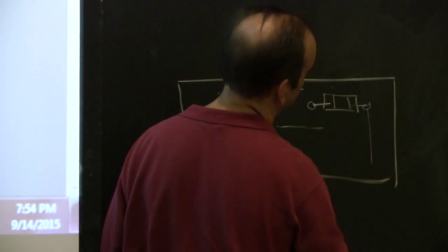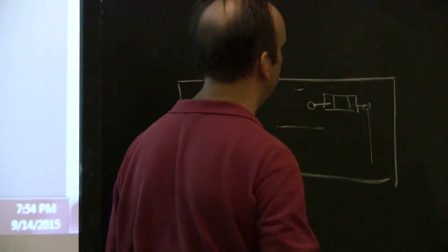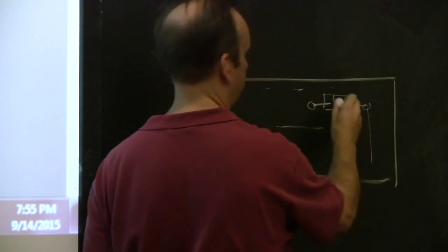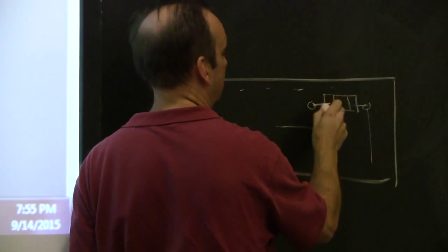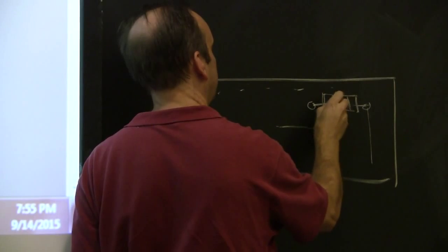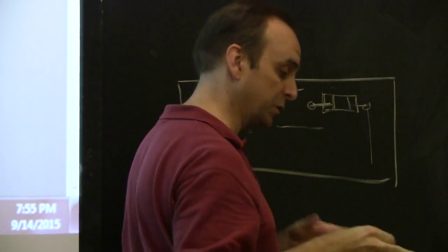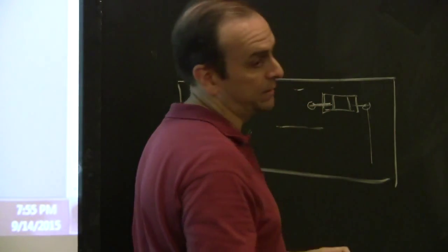If the traces are long, there's probably a tiny bit of capacitance from the trace to the reference layer underneath it. There are parasitics inside the package itself because there's some ceramic material inside the package, but it's got to get out to a little piece of metal on the end and then out to the board. So anywhere there's a discontinuity where the material changes, like a pothole in the road, there will be additional reactive elements.